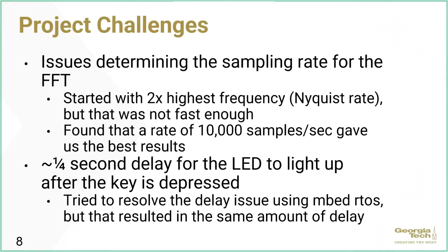Even though we got some desired results, there was another big problem: the keys still had a one fourth of a second delay for the LED to light up after we released the key on the piano. We tried to resolve this issue using the RTOS, so the computation would happen in parallel. But since most of the stuff was sequential, RTOS didn't help us that much. It still had a similar delay.